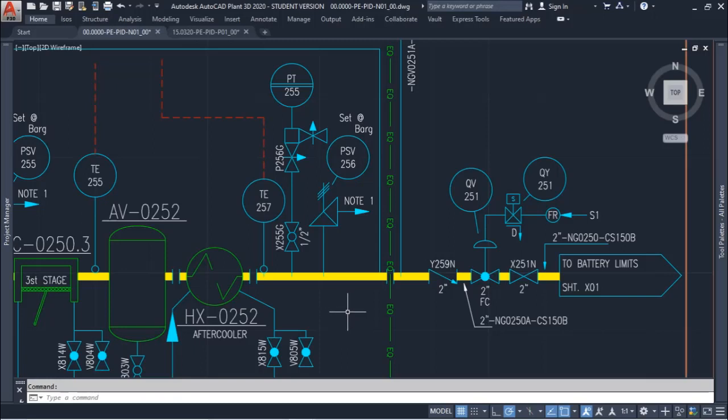It is without a set pressure because it's a preliminary drawing, but if I had a set of, for instance, 100 bar G, I know that something is wrong, because if I'm working with piping material rated for 150 pounds, it means that I can have something around 10 bar G as maximum allowable working pressure, depending on the operating temperature and pressure-temperature rating also.